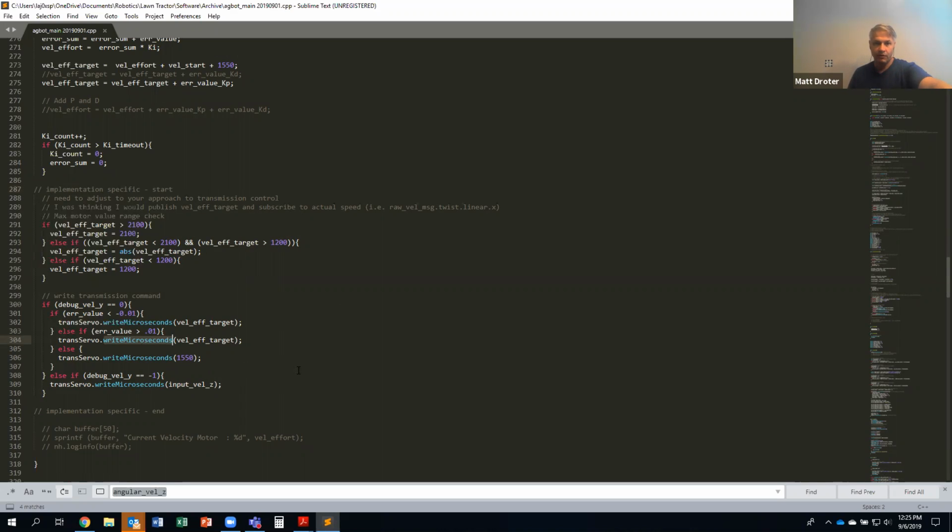One thing I was working on down there is like C291 steer effort target set 2100. Those may be better to be variables that we call out. The implementation should be in one section, like a setup section where they're variables, and then we can adjust those. But your position of where your servo motor needs to be may be different, depending on where you mount it, the length of your mounting arm, and then the lever. Yeah, I can make those variables.